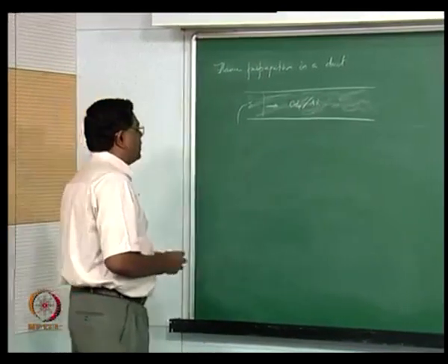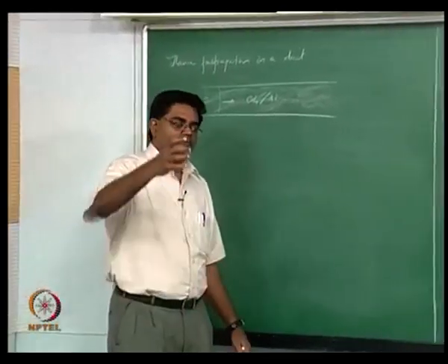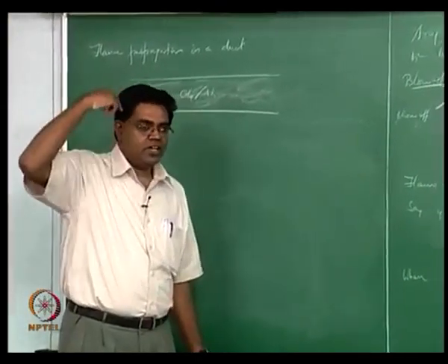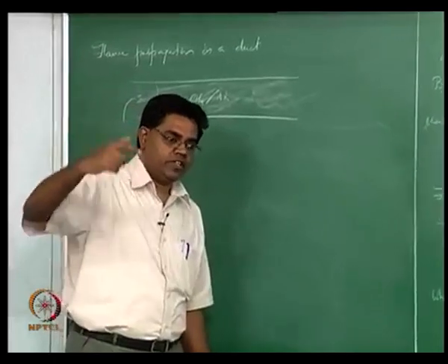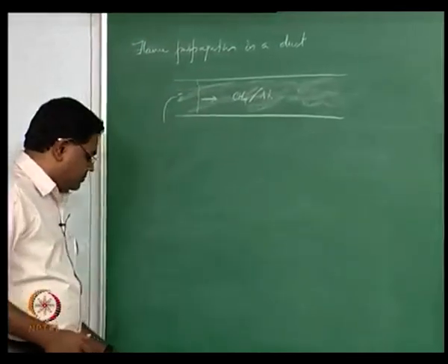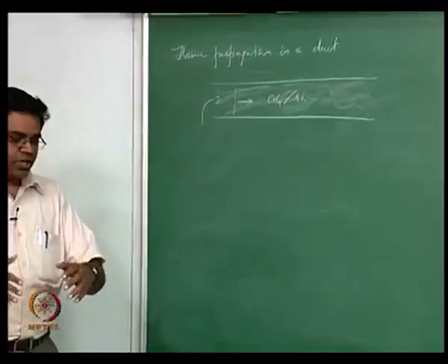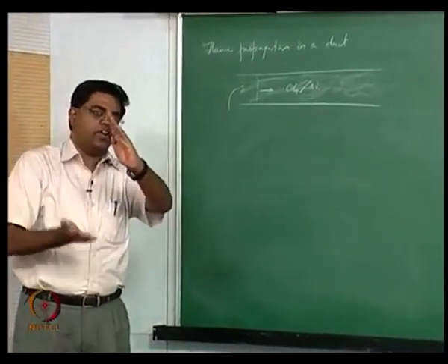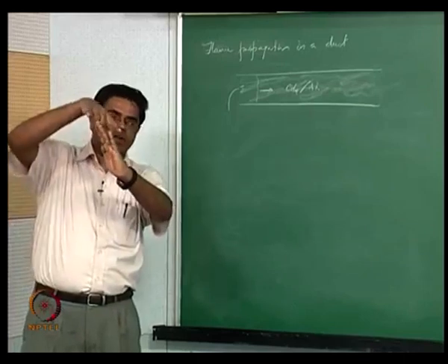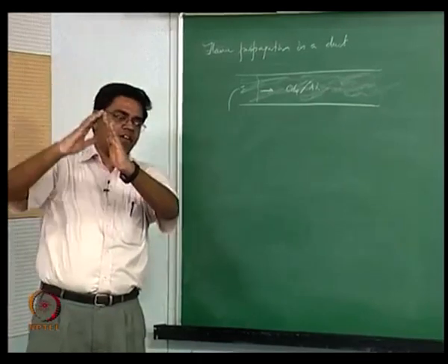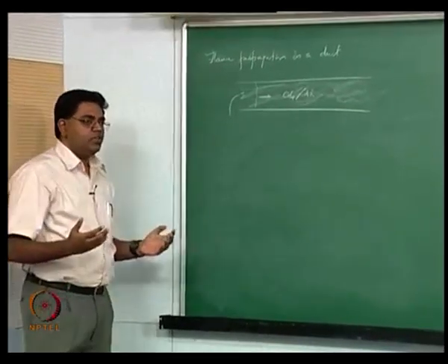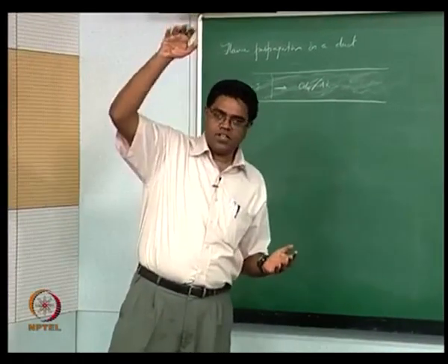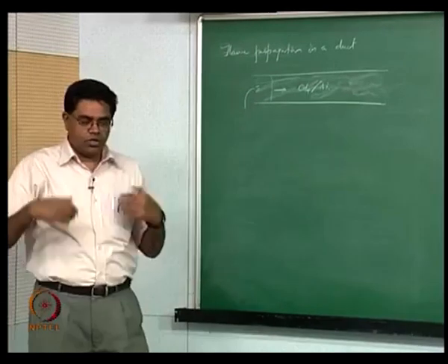So far what we have been imagining is having a burner and then having a flame that is stabilized above it, but implicitly in our minds we have a gravitational field that's acting on this. You have a gravitational field that is acting downwards, and you now have a flame, reactants are coming up here and products are going up there, and this gravitational field is now going to impose a buoyancy effect in which the lighter gases are going to go upwards and the denser gases are going to stay downwards.